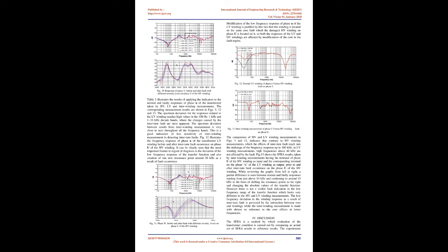It proves that the main characteristic features associated with inter-turn faults extracted from the frequency response measurements, namely displacement of the resonant frequency points to the right and a change in the transfer function magnitude, are discernible for all the fault severity levels in the mid-frequency range of three-phase frequency responses. Furthermore, the change in the low-frequency response of the faulted phase is clearly noticeable for all the fault severity levels.